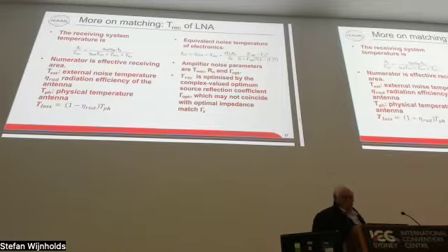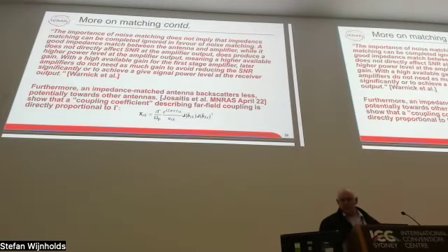Of course, if these two are the same point, or even better, they're both 0, then it's a really nice design. There's a lot of detail over here, which I've really just put in case someone asks for the slides afterwards. There's some very recent work which looks at mutual coupling between isolated elements, or for instance, MWA tiles. In that, and this is now not elements close together, but ones far apart, the impedance reflection coefficient appears there. So the higher the impedance reflection coefficient, the more coupling you may get between far away tiles.